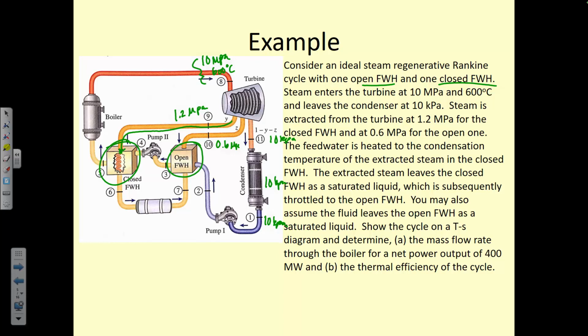The feed water is heated. When it's talking about the feed water, it's talking about the stuff that's coming out of this pump. It is heated to the condensation temperature of the extracted steam in the closed feed water heater. What does that mean?